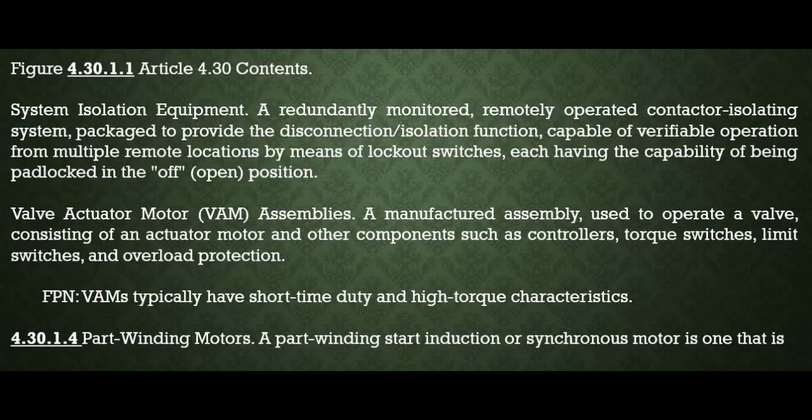It explains special equipment in Article 4.30. System isolation equipment simply disconnects motors from power using remotely operated lockable switches. Valve actuator motor assemblies are factory-built units that move valves and include the motor, controllers, limit switches, and overload protection, usually for short time, high torque operation.